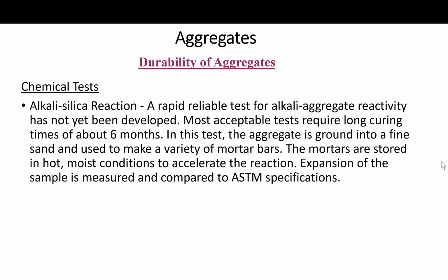The chemical tests: we talk here about the alkali-silica reaction. A rapid and reliable test for alkali aggregate reactivity has not yet been developed. Most acceptable tests require long curing times of about 6 months.